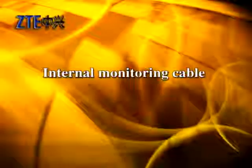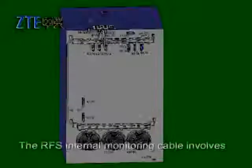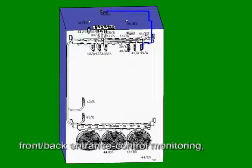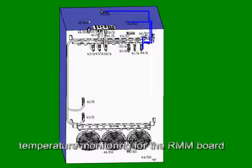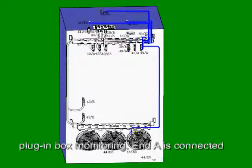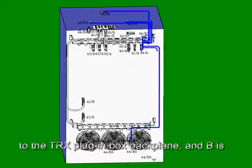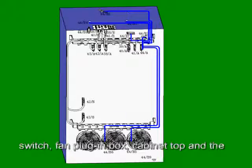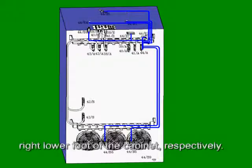Internal monitoring cable. The RFS internal monitoring cable involves front and back entrance control monitoring, temperature monitoring for the RMM board and TRX board, flood monitoring and fan plug-in box monitoring. And A is connected to the TRX plug-in box backplane, and B is connected to the front and back door magnet switch, fan plug-in box, cabinet top and the right lower foot of the cabinet respectively.